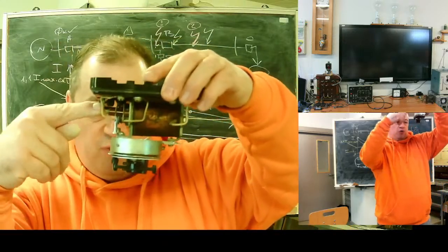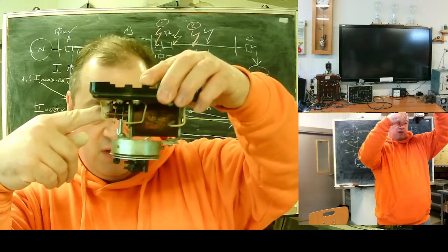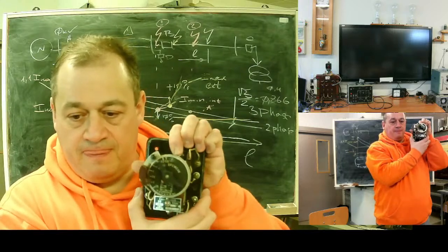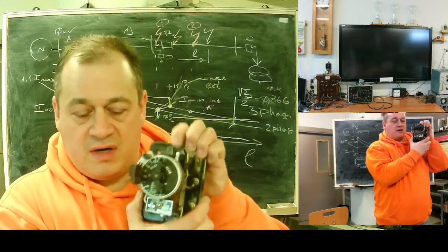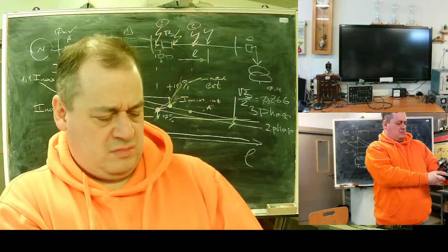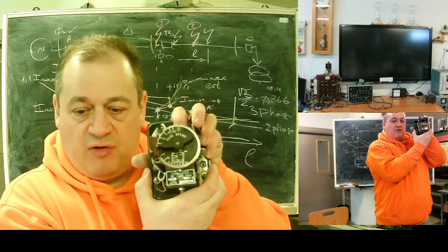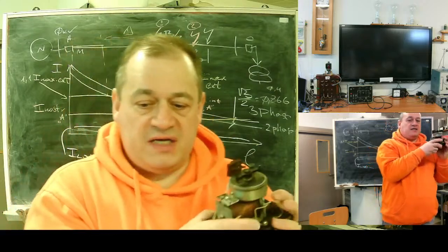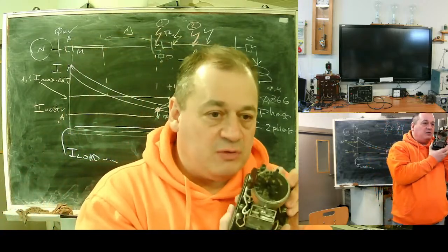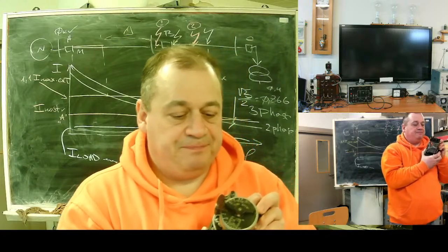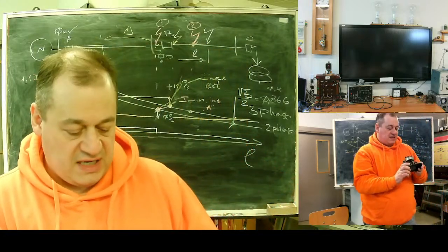If you apply voltage to the coil, the clockwork starts and the relay counts 2.5 seconds and then sends a signal forward. Very simple time delay function. Wait for 2.5 seconds and then send a signal.